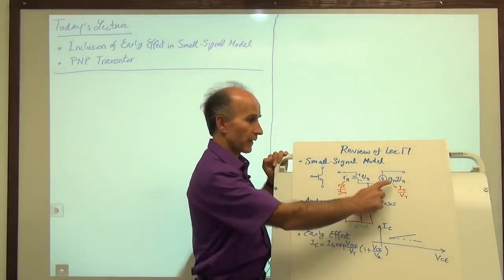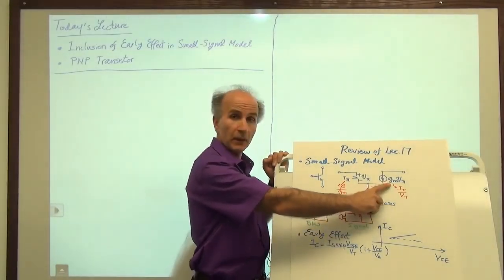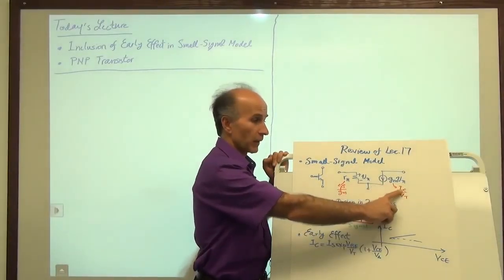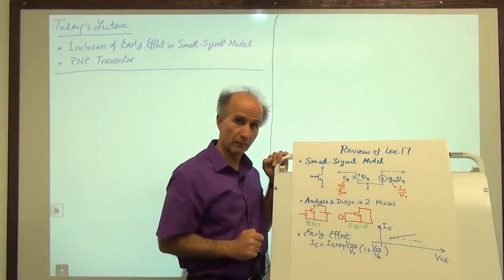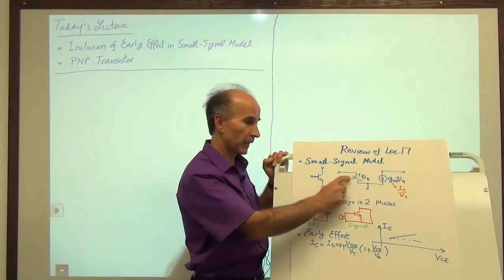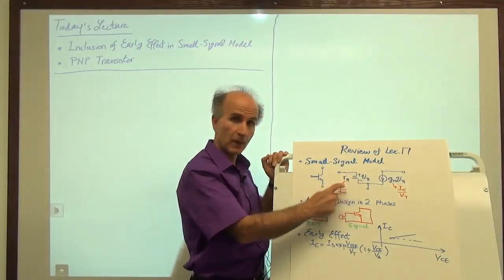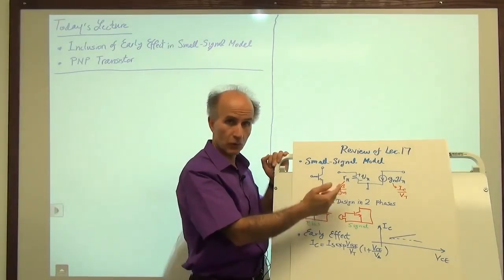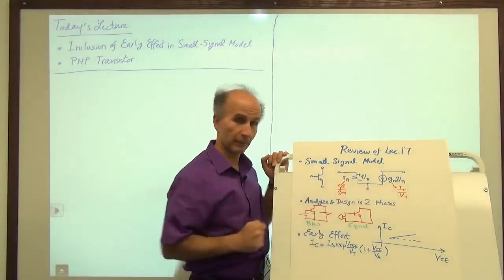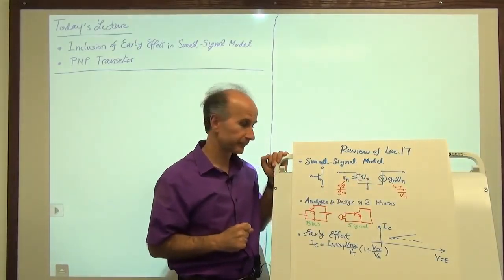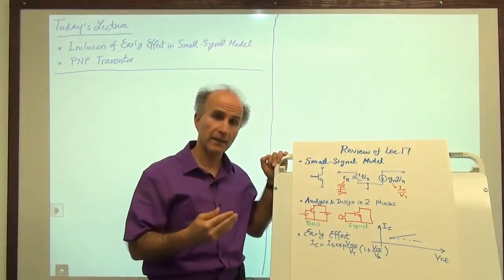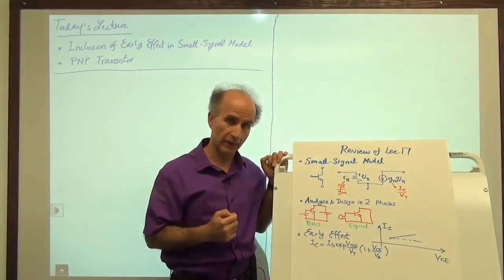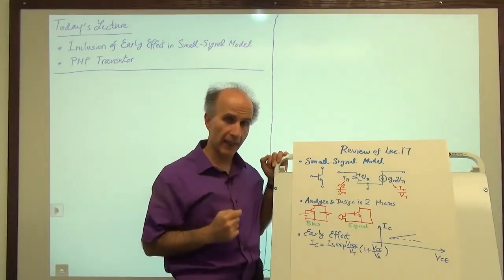So we also saw that gm is simply calculated if we know the collector bias current and the thermal voltage, 26 millivolts, and R pi, this resistance happens to be beta over gm. So once we have gm, we also have beta, we also have R pi. Okay, so what this tells us is that in analysis and design of circuits, we really have two different tasks.